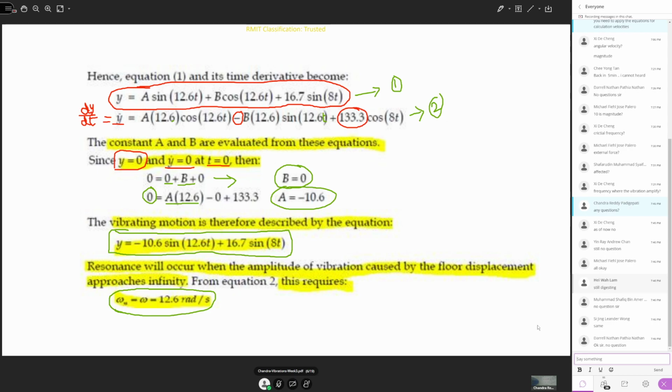Then when we consider the right-hand side as the given external force function, and solve that, you will get the particular integral. So the total solution y consists of the complementary solution plus the particular solution. For forced vibrations, the complete response is the response due to the free vibration yc, the complementary solution, plus the response due to the steady state or the external force, yp.